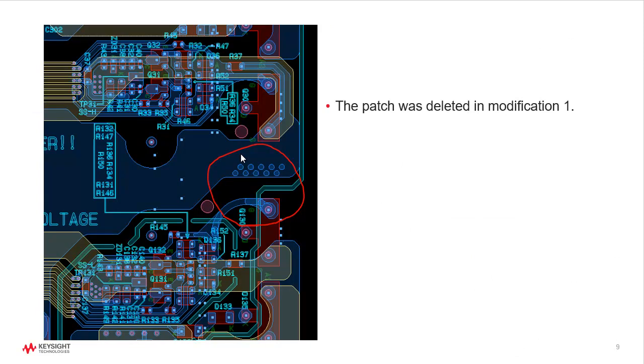Now the first modification we try, we just delete the patch, because it turns out there are multiple paths between these two transistors, and this metal isn't actually strictly necessary in order to make the connection. So if we just delete it, we've cleared our lane for our circuitry, and the connectivity hasn't changed. But we may have introduced some unwanted side effects. So let's go back to those waveforms and see what happens if we just arbitrarily delete this piece of metal.